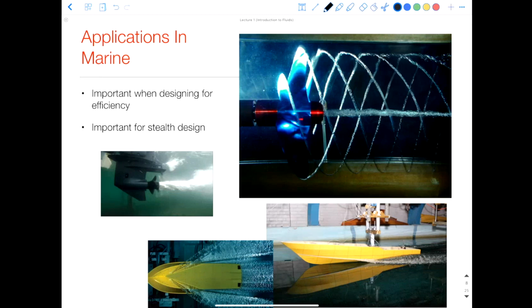And then also in defense, there's a similar thing at the end of a propeller blade. If you think of it like a wingtip, a vortex is formed, and the pressure properties around that wingtip vortex can actually cause something called cavitation, which is kind of what you see in the top right-hand corner here. Cavitation is basically water vapor expanding, and then at some distance away it collapses, and that makes a lot of noise. So if you have a stealth submarine or